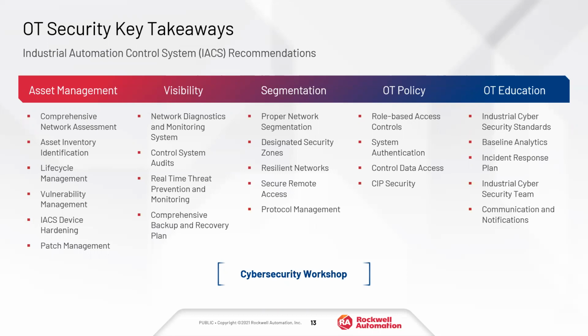The trusted slot option that I was talking about for restricting access to the configuration of the controller through Studio 5000, that would be tied in your ControlLogix environment, or potentially even just turning on FactoryTalk security. That could be used not only at the control system side, but the entire software side of all of the FactoryTalk and Studio 5000 environment pieces. And best of all, everything that I just talked about really requires almost no changes when it comes to licensing or hardware.